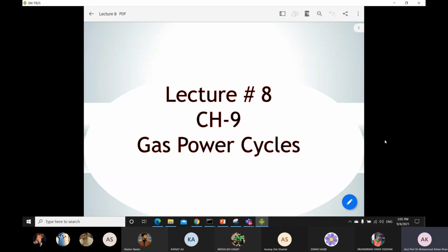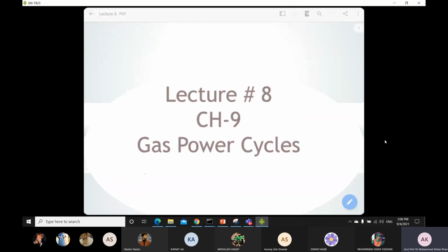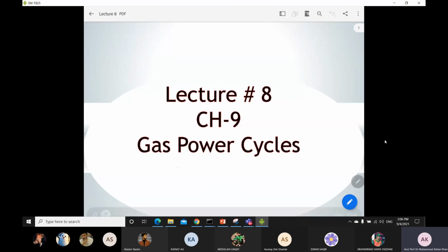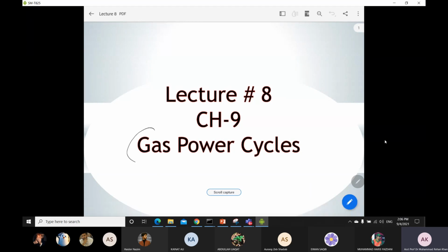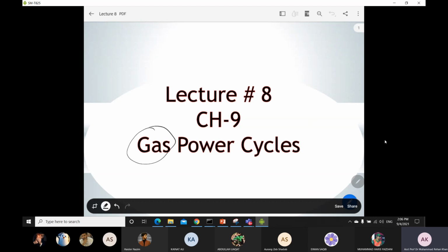Okay, so starting from your chapter number 9 now. Previously we already talked about vapor power cycle. Now we have to go to gas power cycle, which is your chapter number 9. Before starting, we have to know the difference between gas power cycle and vapor power cycle. As I have already discussed in the previous lecture, in vapor power cycle, your working fluid is always in a liquid phase, or it will be in a two-phase region. However, in a gas power cycle, it is always in a gaseous phase. This is the basic difference between gas power cycle and vapor power cycle.